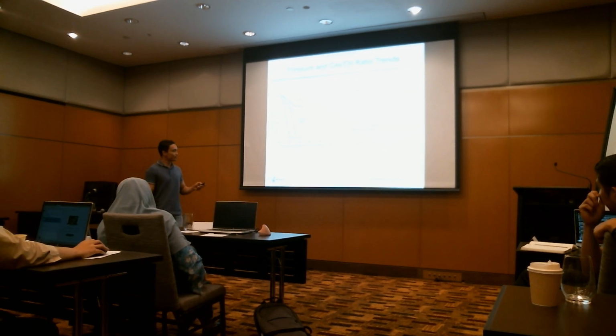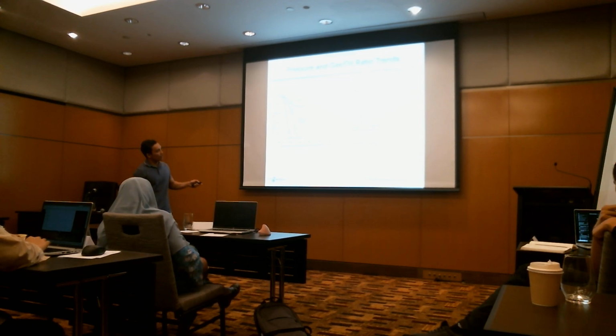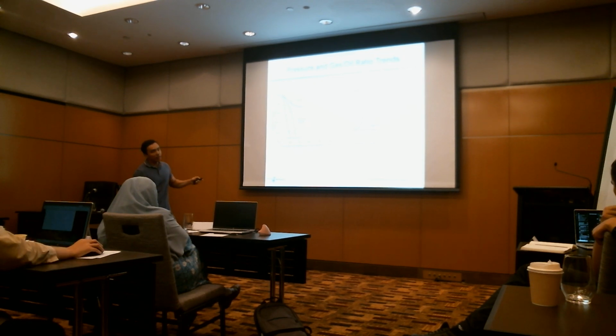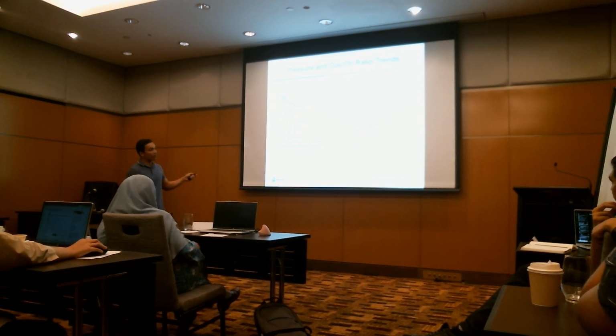The structure. Okay. For the GOR, you can see this kind of trend. You can see a gas cap as compared to solution gas drive. It's going up, right? As you produce. Water drive, because of the high pressure maintained, has a stable GOR. Okay. Now you can have a feel for the comparison between all the drives, right?